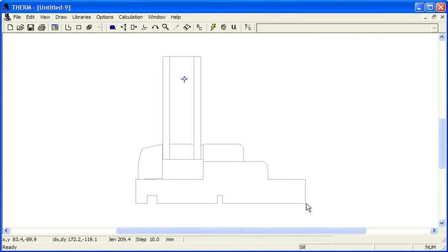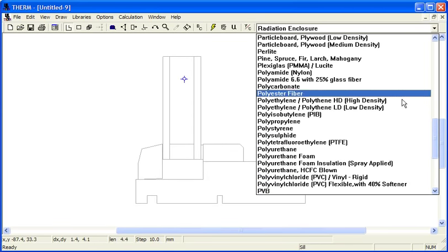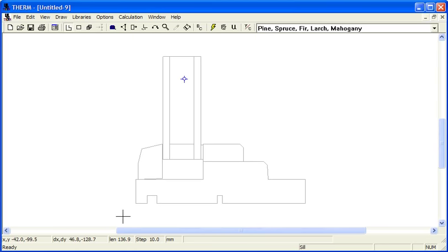So what we have here is the underlay, and we're going to trace these polygons so that we can draw the whole frame cross-section. We're going to start here by doing the Draw Polygon, clicking, and we're going to select the type, and this is wood, and it's pine wood, so we're going to select this here.